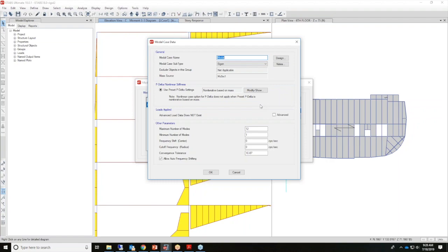Only pertinent mode shapes which occur in the horizontal plane are identified. You're asking about Ritz vectors, but eigenvectors use the full stiffness and mass matrices, which account for the vertical modes. Ritz vectors are a better choice when doing modal superposition. And I'll post the specific detail as to why on the website after the session.